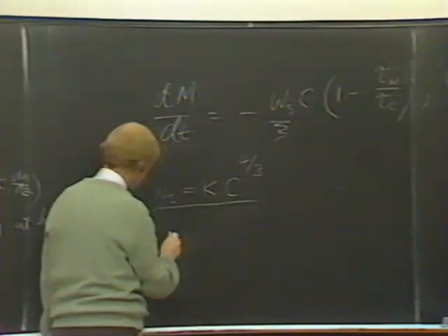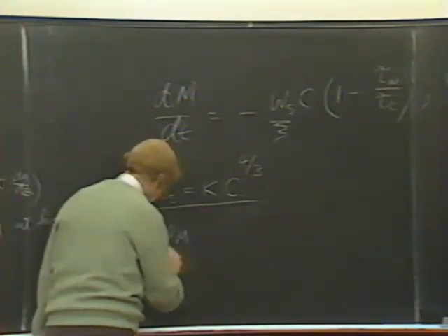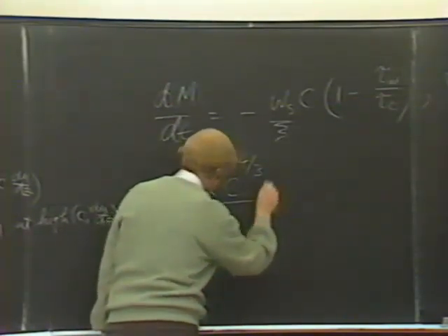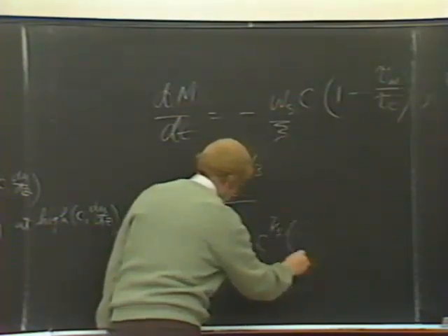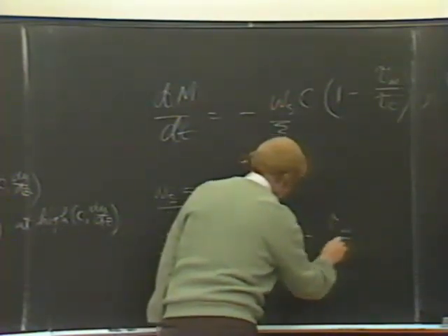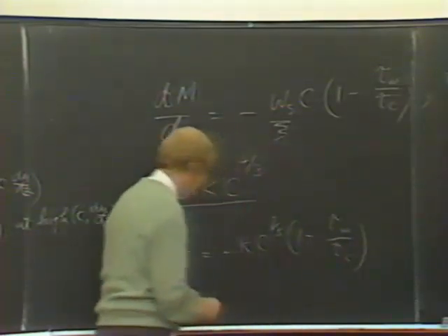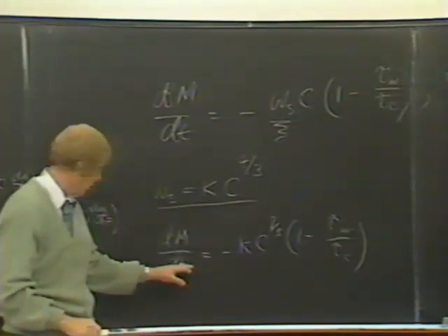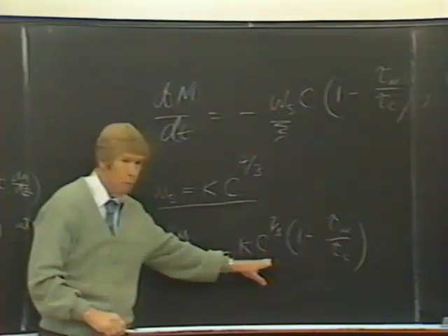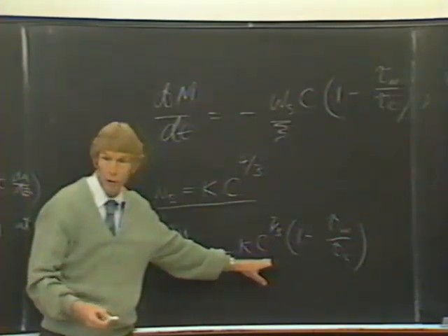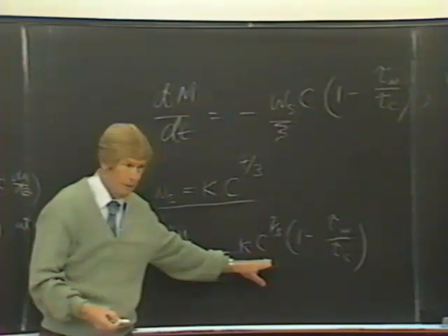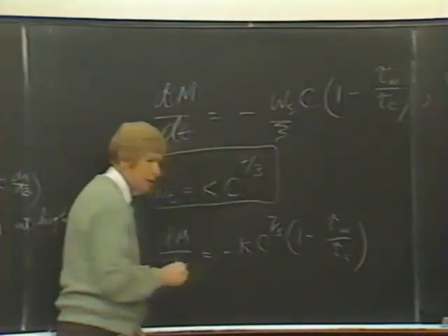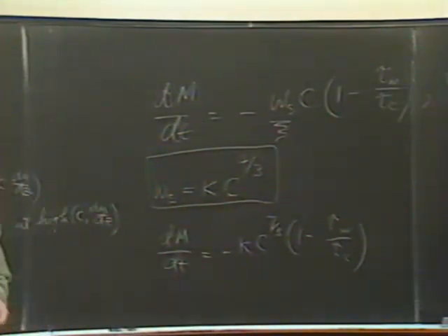Then he investigated the relation between observed settling velocities and concentration, and he came up with W sub S of G equal to a constant, I'll call it A, plus B times G, some linear function of G. But he came out with N of G approximately equal to something greater than 2, 2 plus a very little bit, but not very much greater than 2.